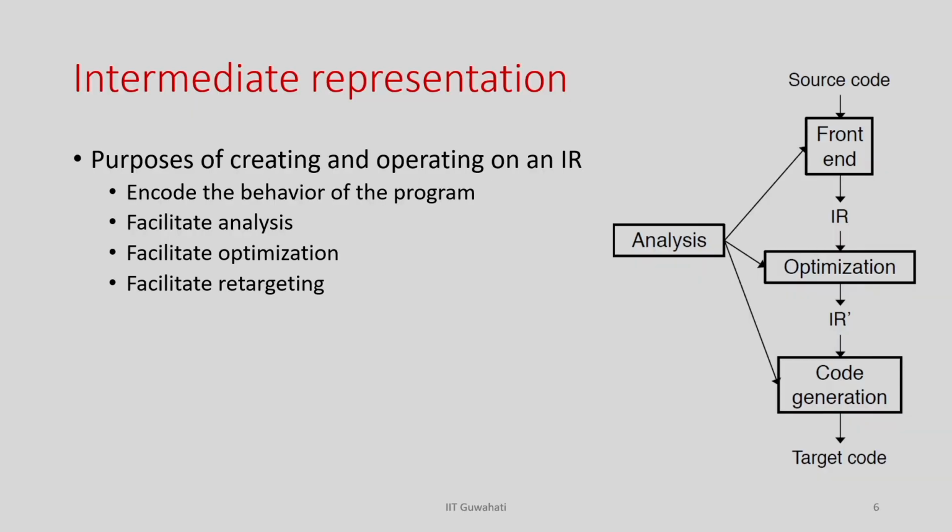As I mentioned, in the pre-processing step you have a C code and you convert it into some intermediate representation, right. The task is that you break the big expressions into 3 address form, identify the basic blocks, the control flow, and the data flow, and then represent that input C behavior in that IR form, in terms of a control and data flow graph, right.